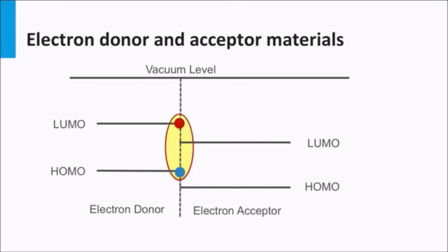Let's make a solar cell out of the conjugated materials. Here we consider an organic PV device based on an electron donor type and an electron acceptor type material. Similar to semiconductor materials, a heterojunction based on two intrinsic materials can be constructed. The junction is based on two different semiconductor materials or different conjugated compounds. Here we line up the electron donor conjugated polymer and an electron acceptor conjugated polymer. The HOMO and LUMO of both polymers can be aligned considering their energy levels with reference to the vacuum level.